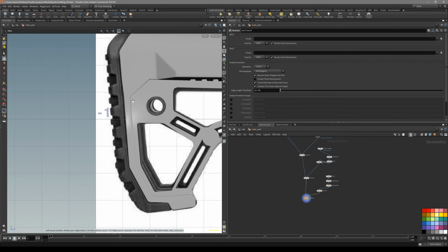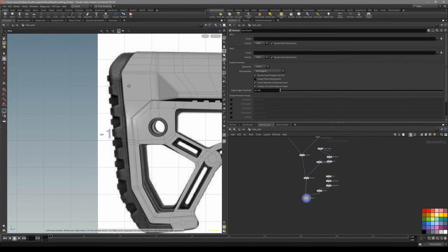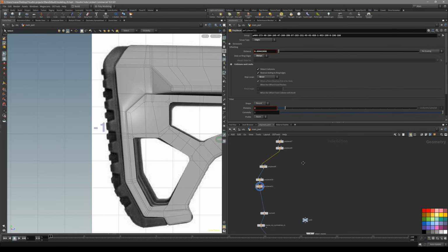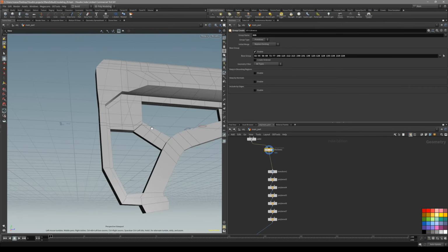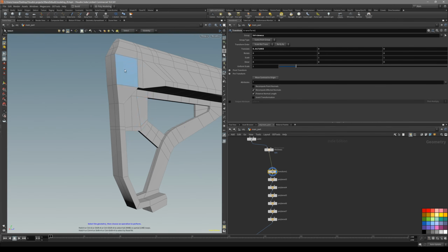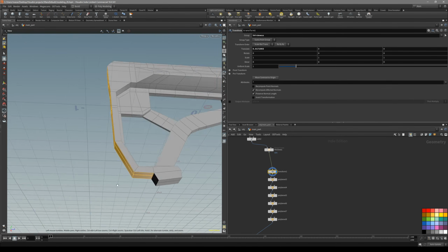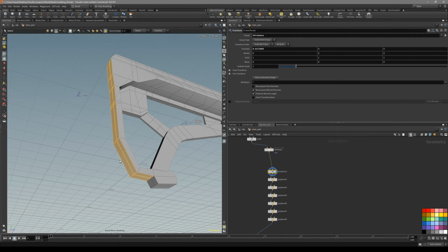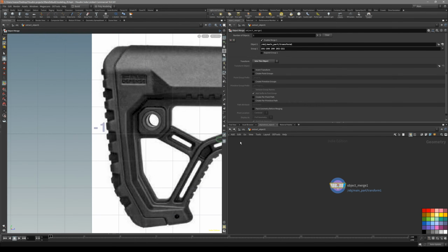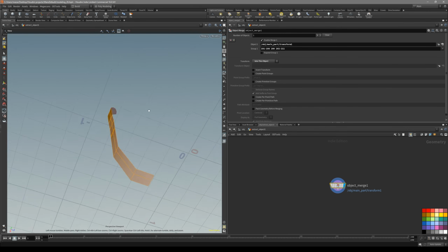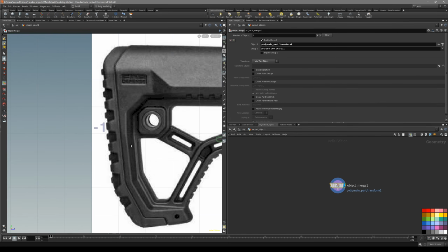Now let's create this back part of the object. For that I want to actually sample this geometry. So what I'm going to do is go outside before we beveled any of the geometry, somewhere in here. Let's turn off select by normal. I want to select all of these, and then in the poly modeling pie menu there's actually extract feature. So extract is going to basically create a new object, geometry, extracting only those points, only those polygons that we have selected.